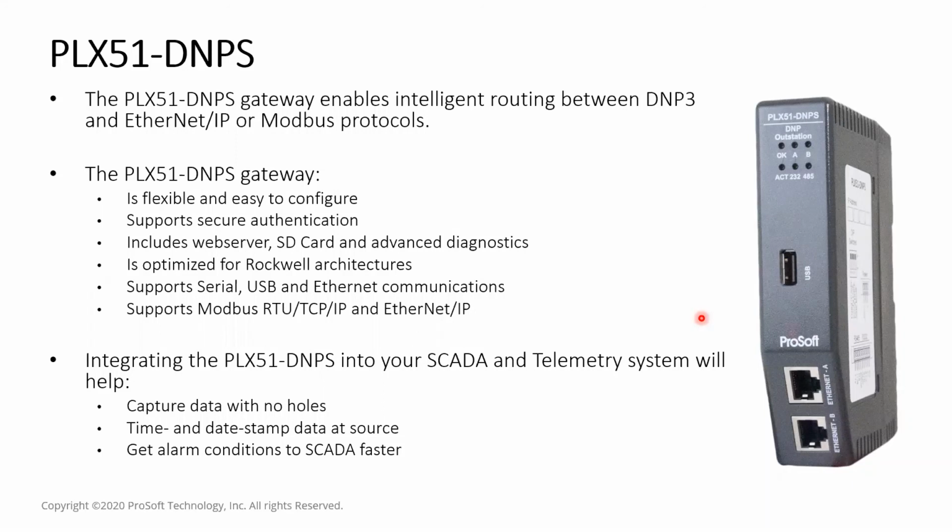So what that means is this module can store, with a date and a timestamp, 900,000 events that are happening at the remote site. So, for example, if your pump changes state, goes on and off, let's just take that as a simple example, it can store that for all that time. And now it is limited to 100,000 of each type. So in the case of this pump going on and off, it can store that 100,000 times, for example.